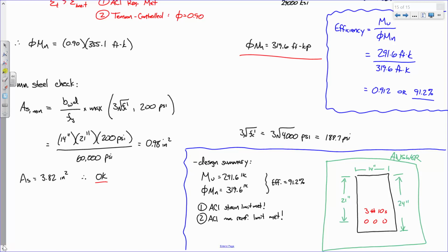That's a great question. Okay, so let's talk a little bit about that. So stirrups, let me say a couple things about that. Beams are going to have stirrups, just period. The reason for stirrups, and don't worry, we're going to spend a good bit of time on that later, is for shear reinforcement. Everything that we're doing now, all we're looking at is the moment, but we haven't even talked about the shear.